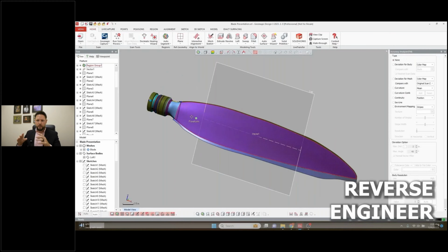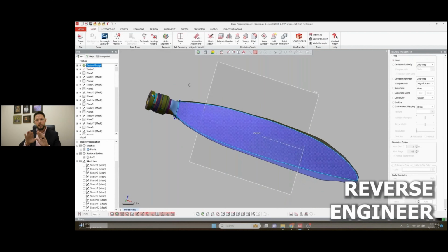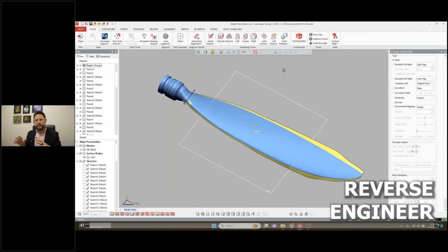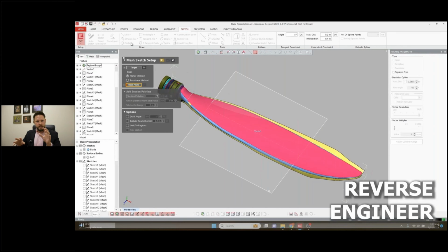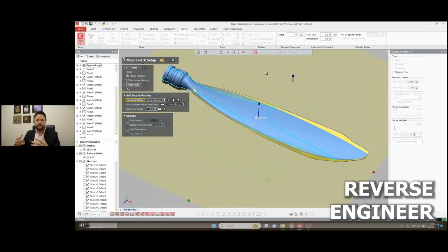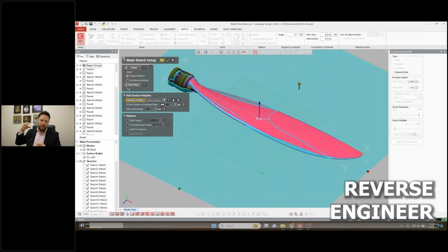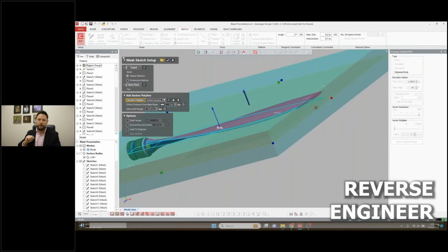And what we're looking at here is the mesh already broken up into these auto segment regions. What the software does is it goes through and applies a region. They're not surfaces, but just areas on the mesh that it recognizes as individual features. And then we'll use those to extract the geometry. All the tools in here are based on this mesh sketch that we're going to go through. It's very similar to a sketch where you would choose a sketch plane and then sketch on it. But in this, we've got a 2D cross section that is going to cut through the mesh. We can also pull what we call a silhouette range and get a 3D profile, because we want the full profile of that outer edge of the blade.